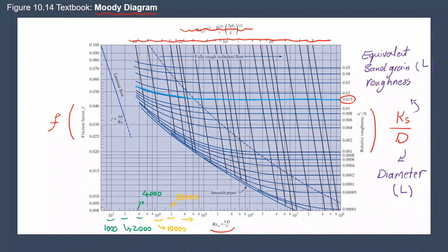The other term that you can find, on the very left-hand side of these graphs, you have your equation for laminar flow. And you can see the line for laminar flow is strictly linear, meaning that F for laminar flow only changes with the Reynolds number, as you can see in this equation. However, the lines for other pipes, for turbulent flow, as you can see over here, are curved. Take a look at this line, for example.